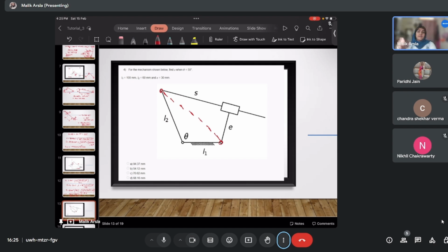In a forward kinematics problem, suppose you have been given a robotic manipulator, in that case there will be some joint angles which you want your robot to move to, and the end effector position will be your output. So if your end effector position is given and you have to figure out the joint angle for that position, it means it is an inverse kinematics problem.